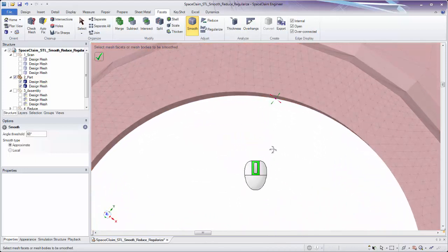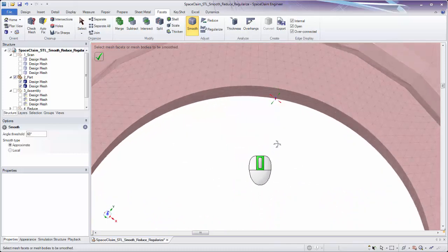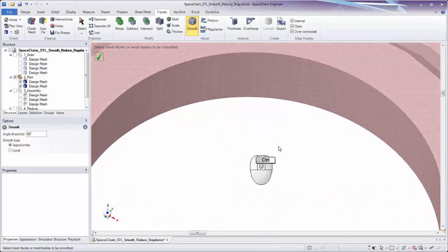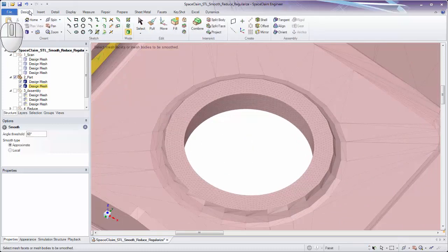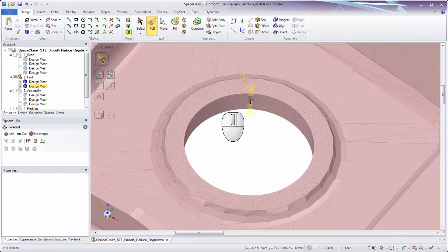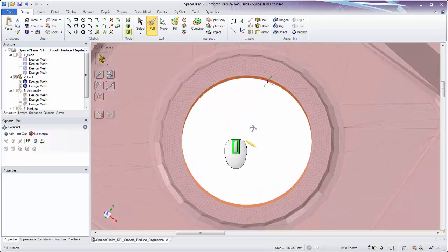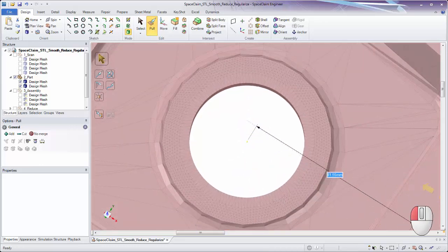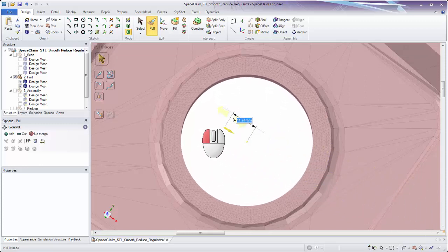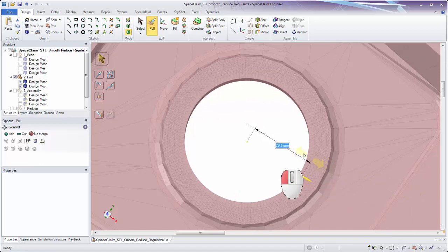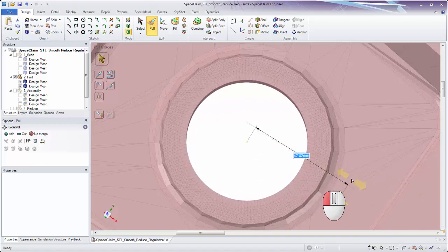And you can see that both on the top, middle, and bottom of this hole, it's nice and smooth. And if it happens to be the wrong size, you could always use the pull tool in the design tab, double click here, and you are now able to pull this hole in and out in order to change the size. There are tutorials on using the pull tool in order to edit an STL found in the same section as this tutorial.